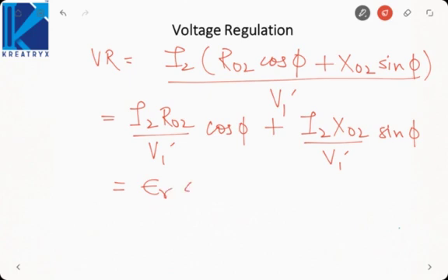It is per unit voltage drop across resistance plus per unit voltage drop across reactance. So this is my voltage regulation, and you can multiply it by 100% to get it in terms of percentage. Now, as voltage regulation denotes the voltage fluctuation, what I want is the voltage regulation should be as low as possible, so that the voltage fluctuation between no load and the full load condition is pretty low. So we want the fluctuation to be less, that means the regulation should also be less.